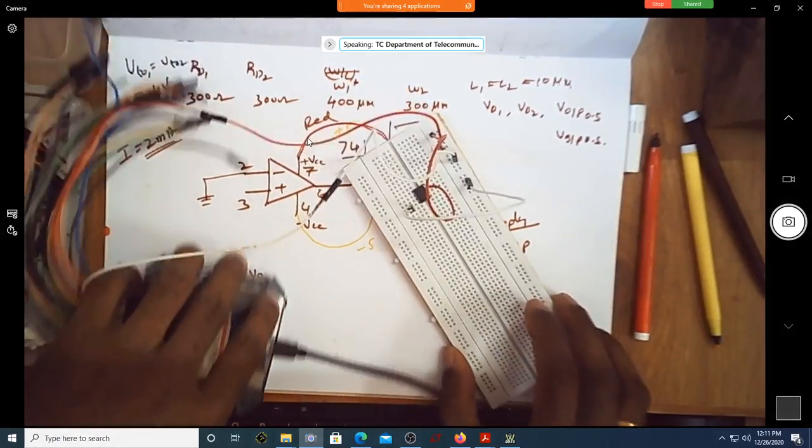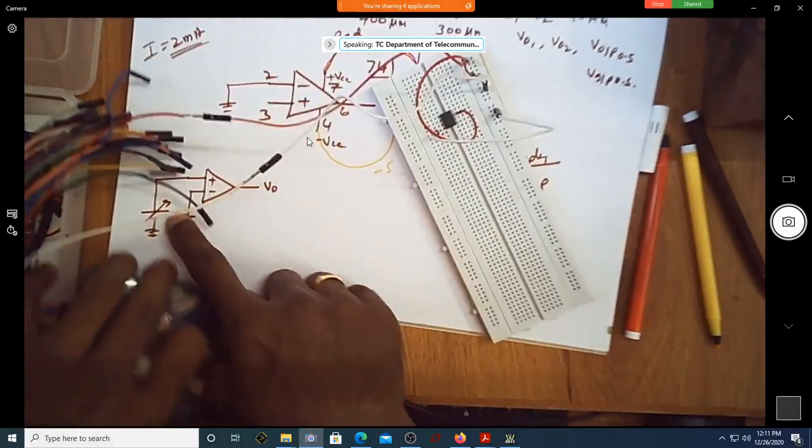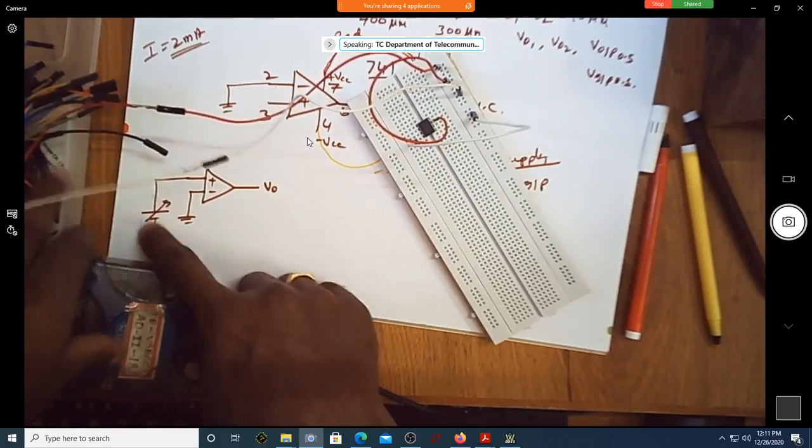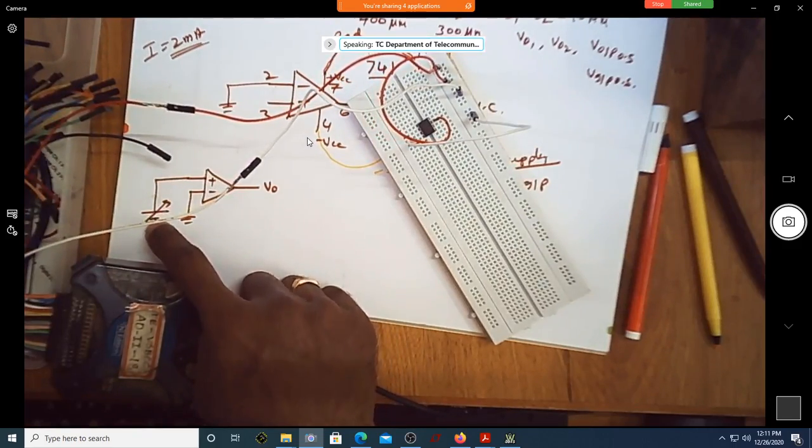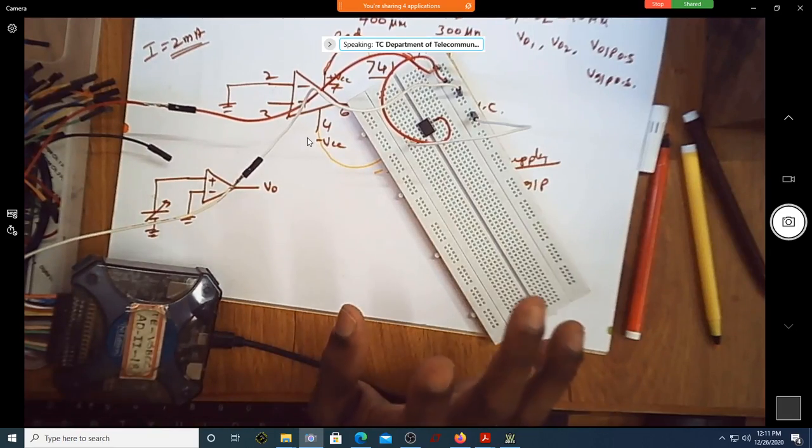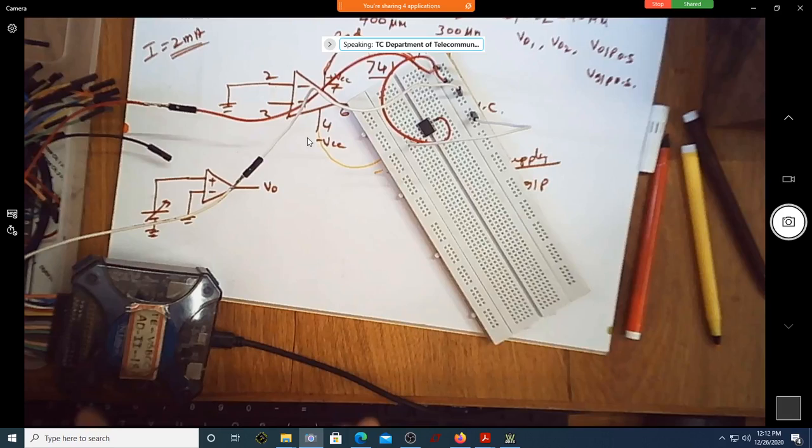Next you can see I need to realize this circuit. So this is my input. See, now there is a difference between input and power supply. Power supply is plus V and minus V. Input is the wave generator. Make this distinction very clear. Supply is for the entire circuit. Input is wherever you want to give the input. It can be a sine wave, a DC voltage, a square wave, a triangle, it can be of any shape. Done?